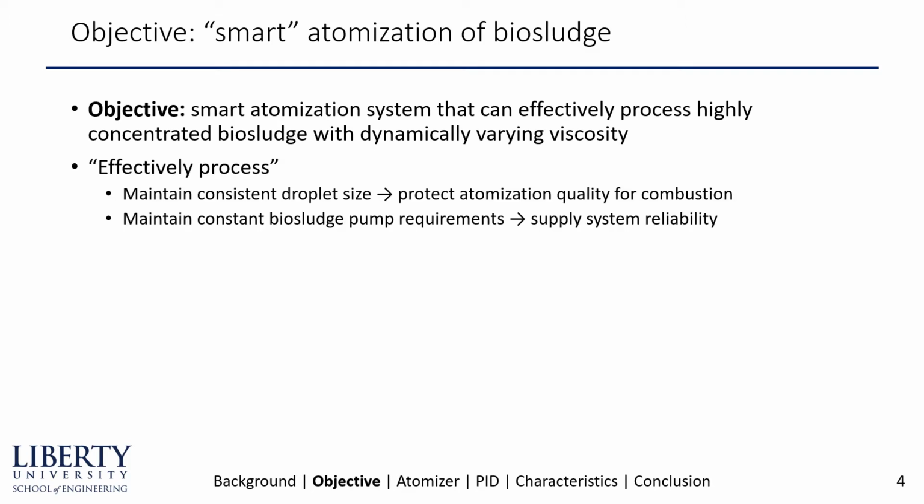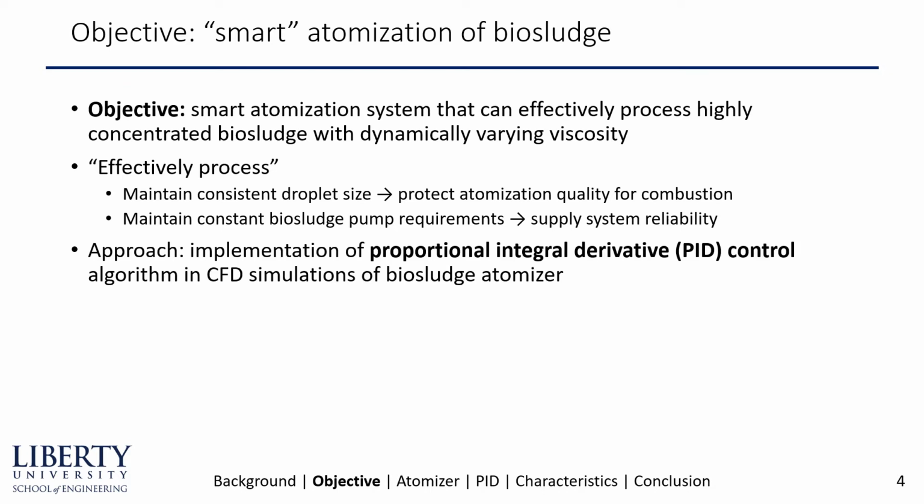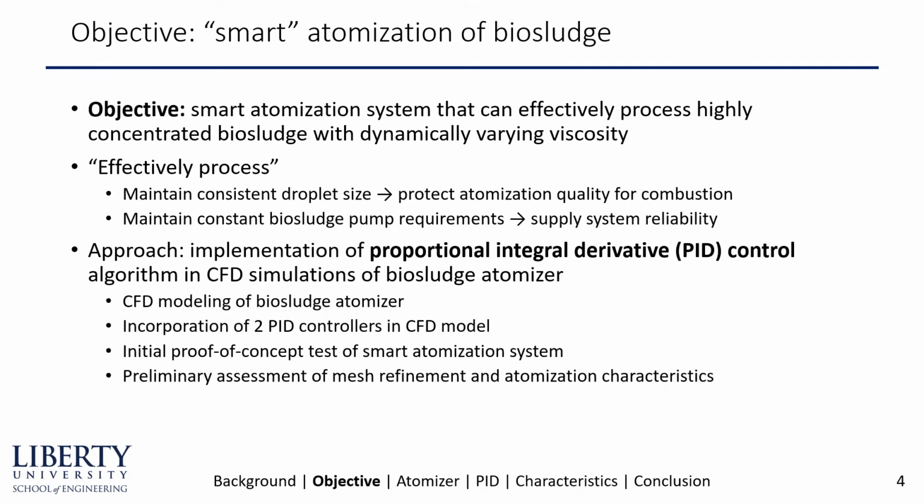When I say effectively process, I'm talking about two things: maintaining a consistent droplet size to protect atomization quality for combustion, and maintaining constant biosludge pump requirements to supply system reliability. Our approach is implementing proportional integral derivative, or PID, control algorithms in CFD simulations of a biosludge atomizer. So this involves CFD modeling of the atomizer, incorporating two PID controllers in our CFD model, an initial proof of concept test of our smart atomization system, and preliminary assessment of mesh refinement and atomization characteristics.